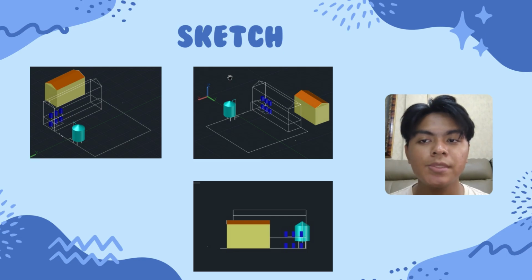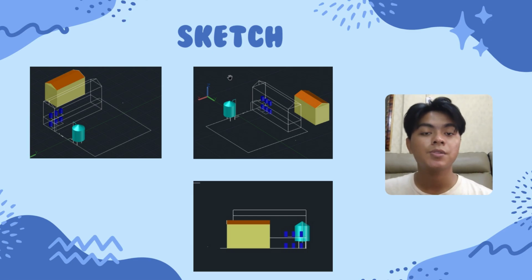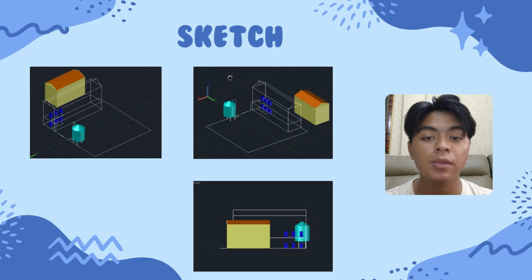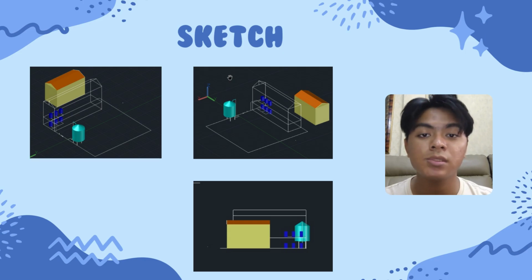Alright, so this is my sketch. It shows a plan of the pipe system connected from the main tank to the 6 toilets in the school. These 6 toilets are used by 150 people, including students and staff in the school. After the calculation and estimate carried out, we have prepared a tank with a 10,000 liter capacity of water, with 9,000 liters for daily use and 1,000 left for emergency use.